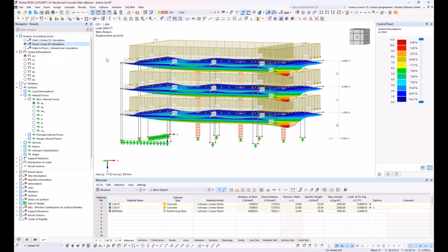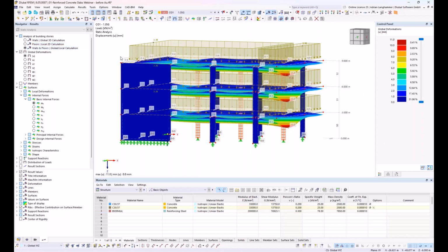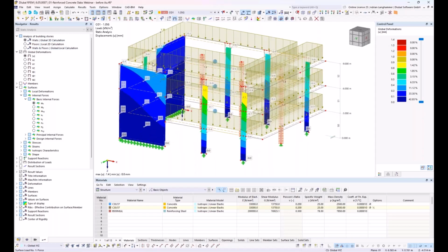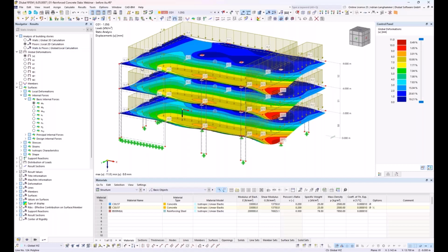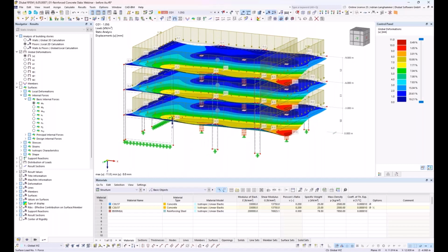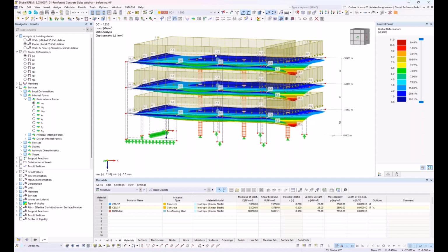Yeah, I also will show another point. The program, as I mentioned, calculates the walls connected via a rigid diaphragm, and the floors, let's say, as separated 2D positions, and it also calculates some load transfer based on a submodel which is calculated in the background.